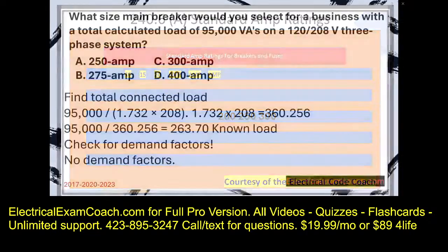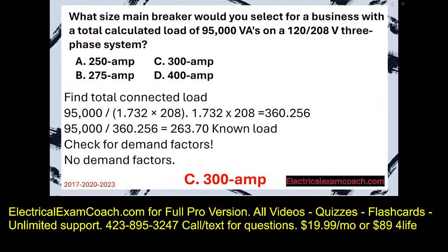And this is where the beauty happens. We're going to now put this on a 300 amp breaker instead of, like in the previous question, a 400 amp, meaning that we'd have to have larger wire in the previous question, which may lead us to have larger pipe, which we may end up with a larger cost of overall project. The beauty of three-phase is the numbers come down. So this one's on a 300 amp service, which means we can put it on smaller wire, which might mean we can put it in smaller pipe, which might end up having a smaller overall cost.